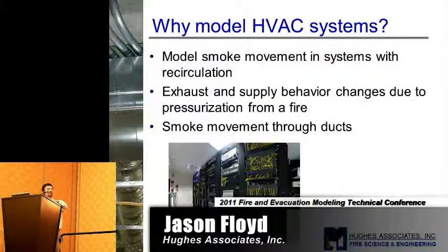What was the motivation? One motivation was that we're seeing usage of FDS in places like data centers, where you have lots of cooling capability present to keep the computers from overheating, and typically these do a lot of recirculation of air inside the space. And they'll do smoke detection, for example, in the ducts, or also spot detection in the space. And so the ability to track smoke as it moves through the HVAC system, circulates back in, more smoke added, can improve your ability to model detection times.